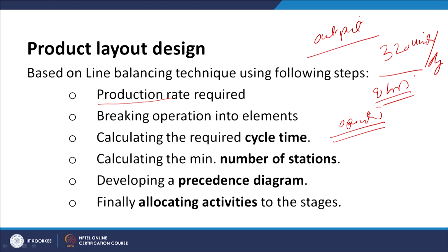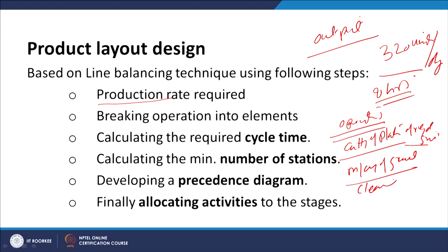Let us say some weld joint is to be developed, then it will start first of all with cutting of the plates to the required size, then it will involve machining of grooves, then cleaning, then the tacking operation, then welding, then a chipping process. So, for developing a weld joint, these are the different steps which are to be performed.